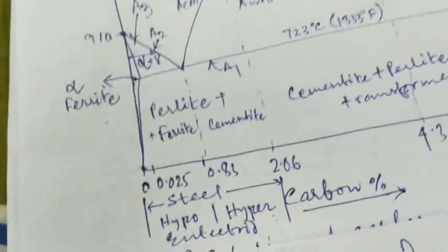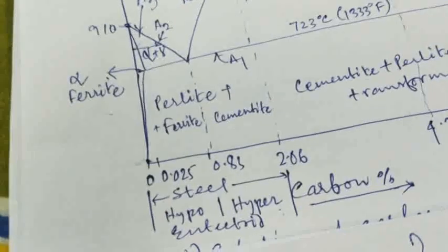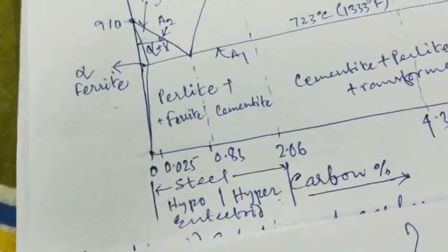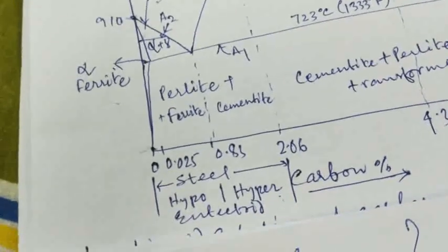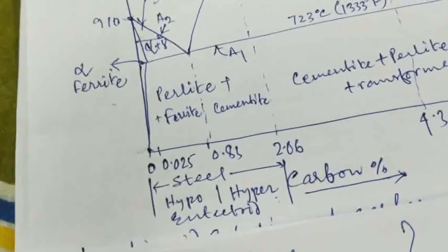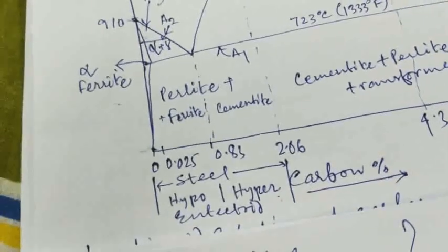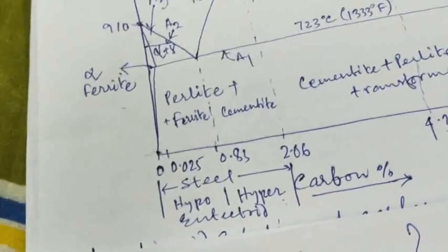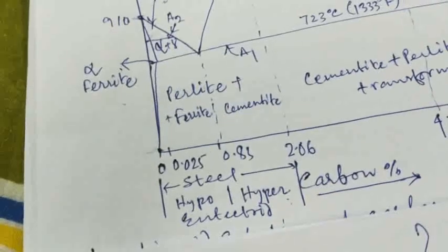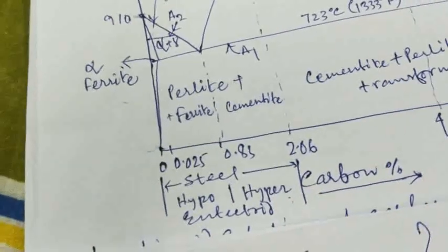Isothermal annealing is also beneficial to achieve uniform organization and performance. However, it is not suitable for large section steel parts and large batch furnace materials because isothermal annealing makes it not easy to achieve the isothermal temperature of the internal or batch workpiece.